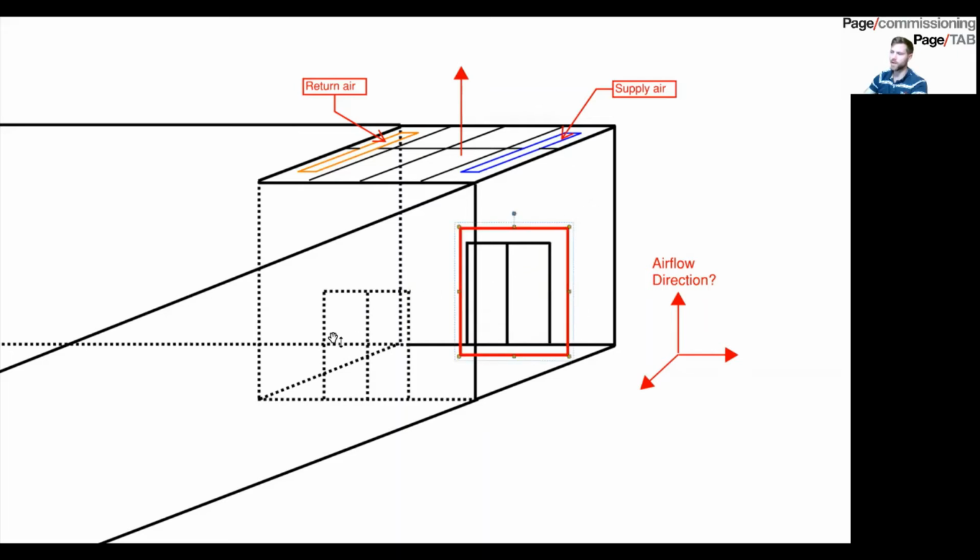And it can't come through that door, so it starts trying to come through this return. I know we showed a transfer duct in this area, but in actuality, the walls did not go to deck there. They were open, and that allowed a lot of airflow through that area. So much air was trying to flow through at certain times of the day that it would pull the ceiling tiles up so that it could get back to the air handler, essentially, or the exhaust fan.